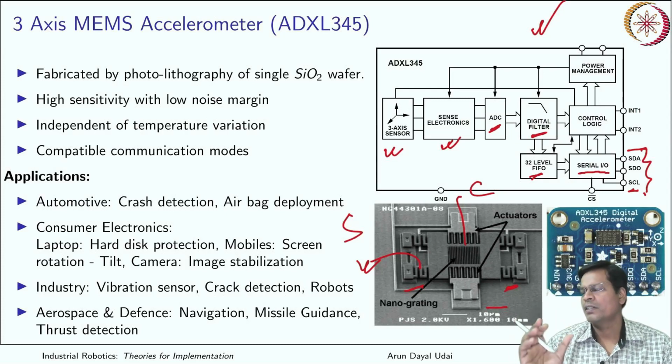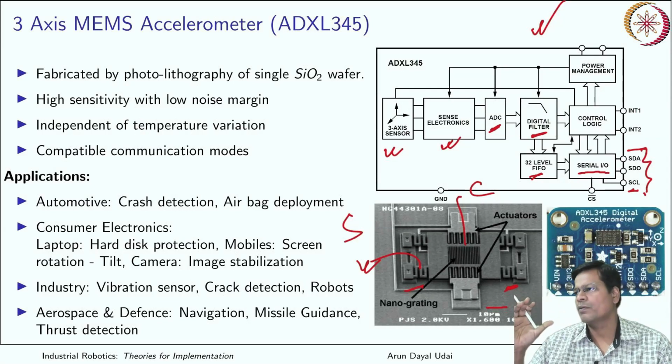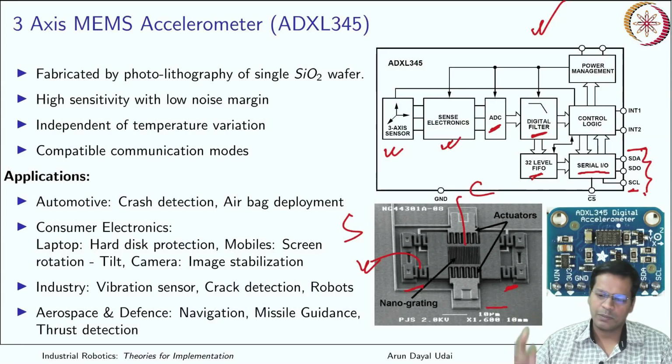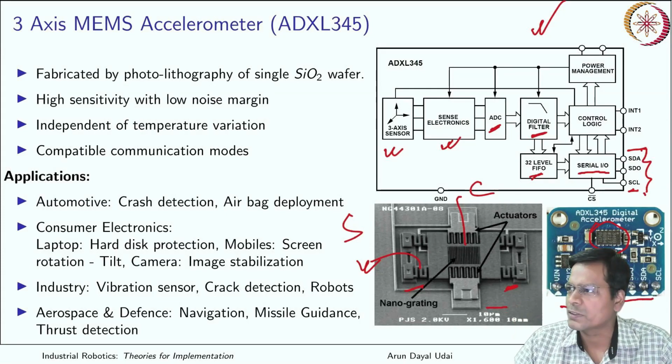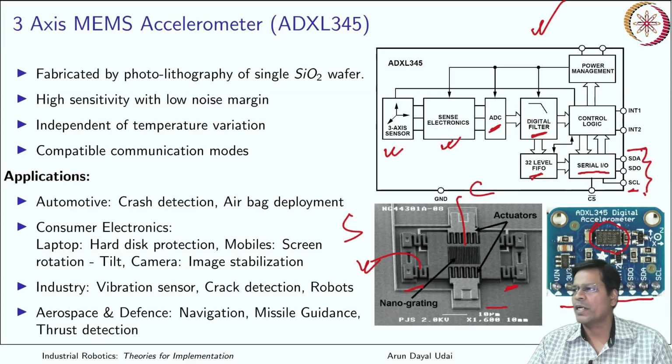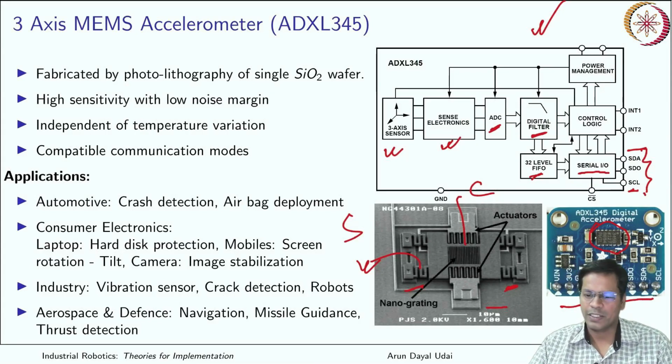So data may be in 8-bit, 9-bit like that. Normally it is 8-bit. So if at all you have to read a big value like in 16-bit, then you have to read 2 bytes or something like that. So that is how it works. So overall this device is sitting somewhere over here with some external electronics also, and now it is ready to be integrated with some other device like a PLC or a microcontroller or a PC or anything like that.